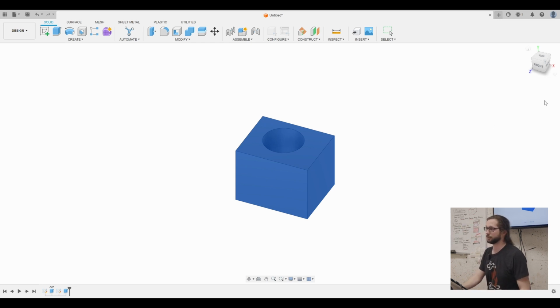I have choices of formats. I can save it as a 3MF. I can save it as an STL. Then if you hit OK there, down here you have an option to save it on your computer. Now you can save it anywhere, and then you can re-import this later using the open function, and it will reopen that.